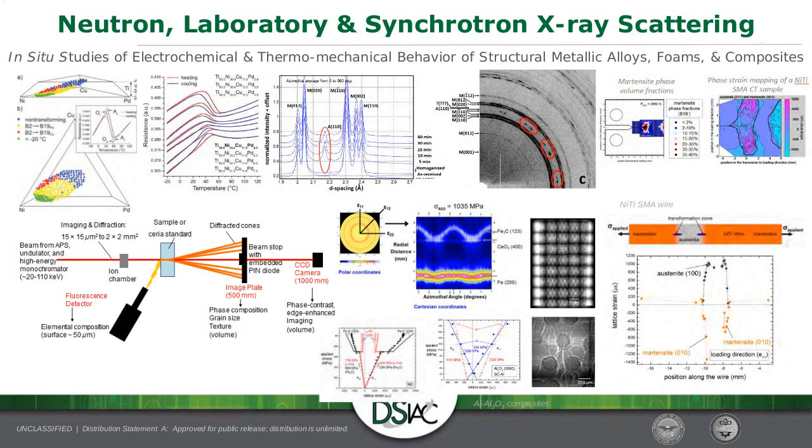Many research, or is there a potential for using SMAs to couple materials with dissimilar CTE? So they do make coupling devices for shape memory alloys. They're nickel titanium niobium. This is done at my former company ATI. Within those, you sort of get a one-time strain, and then you get the shape memory effect. So what that means is that we wrap it around, it sort of creates a strain around the material, and then it has the ability to move through the phase transformation so that it maintains sort of some mobility, or flexibility, but keeps it sealed.